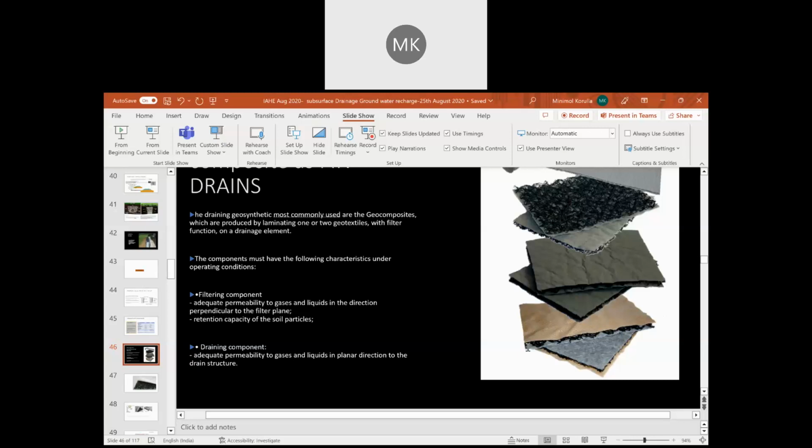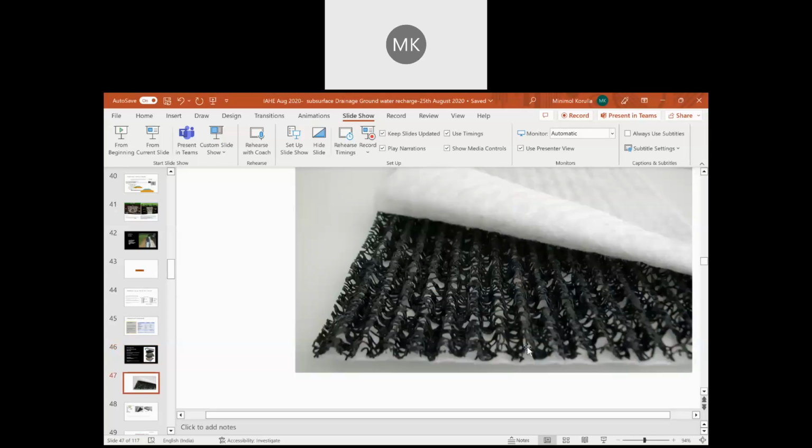Now I told that we can go for a drainage composite with one side geomembrane and the other side geotextile, and in between a drainage net that can be used as a capillary cutoff. But just like I told that a geotextile also can be used as a drainage layer, the same way, a geomembrane also can be used as a capillary cutoff. We don't have to always go for a complete drainage composite. Just an HDPE sheet can also act as a capillary cutoff.